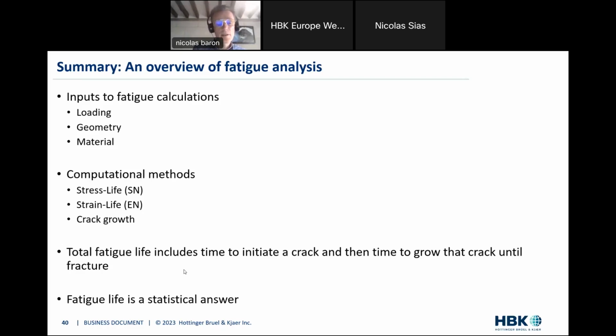And the last point is that fatigue life is a statistical answer. We are going to see that when we look at the curves, the SN curve or the EN curve, the Wöhler curve somehow, how these curves are characterized, it will be very clear that fatigue is a statistical answer. So there is some variation, and we need to fit the laws in the way we characterize things. But never forget that fatigue is a statistical result, and as such, there are some things to consider when giving a result in terms of fatigue, and more on that also in the remainder of this presentation.